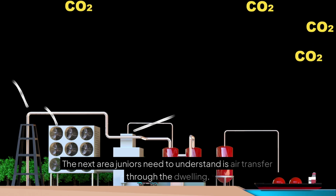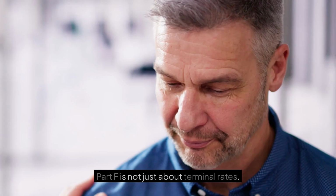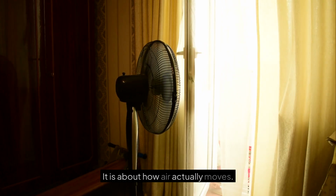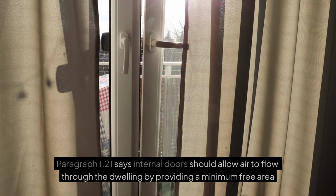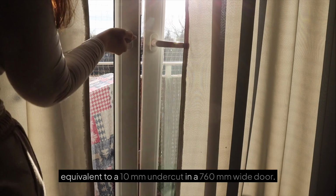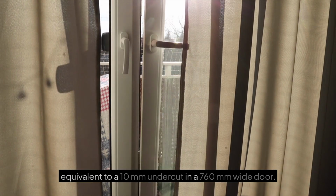The next area juniors need to understand is air transfer through the dwelling. Part F is not just about terminal rates, it is about how air actually moves. Paragraph 1.21 says internal doors should allow air to flow through the dwelling by providing a minimum free area equivalent to a 10 mm undercut in a 760 mm wide door.